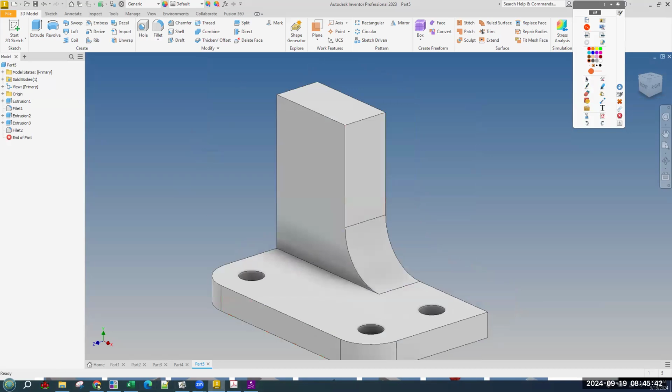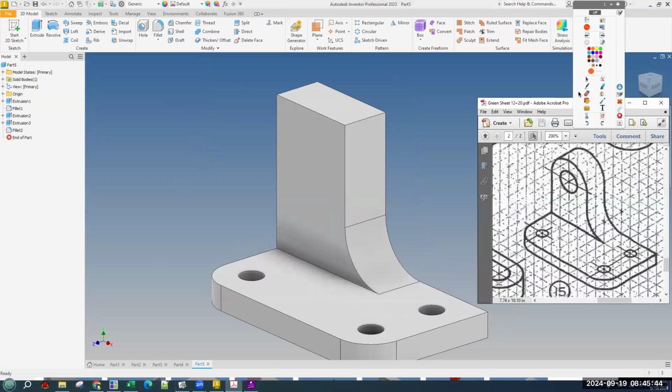And then the top part, we can continue with our awesome filleting of the top edge, which, because it's a smooth surface, we know that it's 4 across, which is the same thing as before, where we make a 2-inch radius fillet and a 2-inch radius fillet, and it smooths it over. And then we'll put a sketch on the front and make our circle with the same center mark, diameter 2, and cut extruded all the way back. I'll do that real fast.